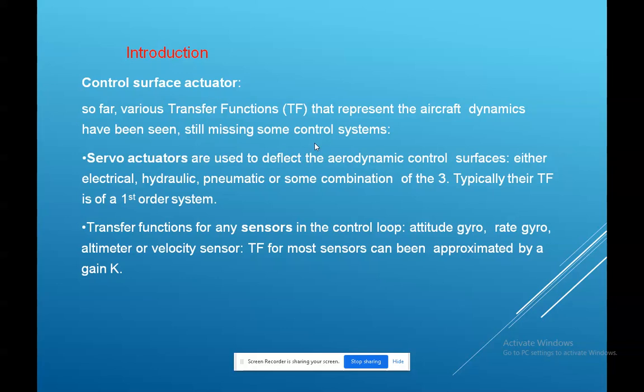So the servo actuator deflects the aerodynamic control by electrical means, hydraulic means, or pneumatic, or some other combination, electrical and hydraulic, electrical with pneumatic. In that way it will be controlling the aerodynamics.